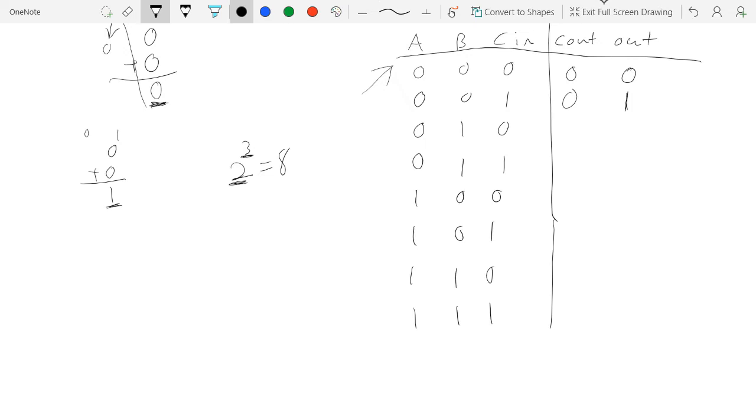You can save some time and look at the combinations in the circuit where I'm only adding up 1 here. Fundamentally, whenever you're adding up 1, it doesn't matter if A happened to be 1, or B happened to be 1, or the carry-in bit was 1. If the sum happens to be 1, it's going to be the same. For example, if we say this happened to add up to 1, we can look at all the other cases in the circuitry as well. This adds up to 1, and this adds up to 1 as well. So to save some time, we know that the carry out and the output bit are going to be exactly the same. I can copy this down: the carry out is 0 and the output bit is 1 in all cases where I add things up and get a 1.